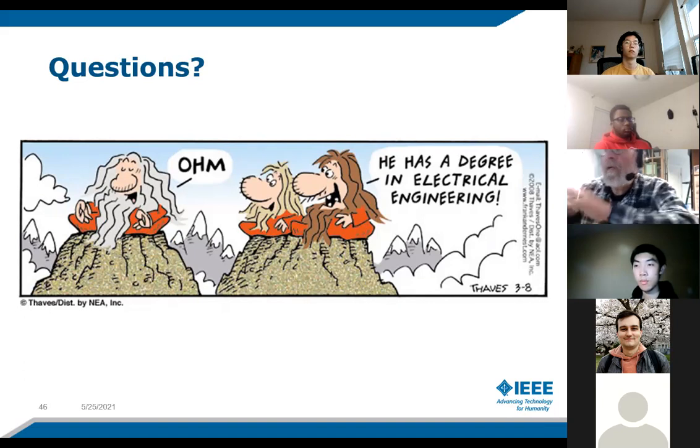And it will collect that data and turn around and export it to another device with Bluetooth instead of with Wi-Fi. The advantage is the Bluetooth stuff is probably much lower data rate, but it's probably also much lower power as well. And if the application that you're exchanging data with doesn't need to deliver a lot of data, Bluetooth might be more effective. Certainly if you want the whole system to last longer.